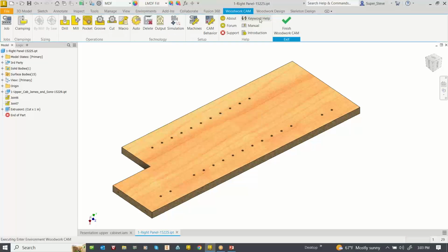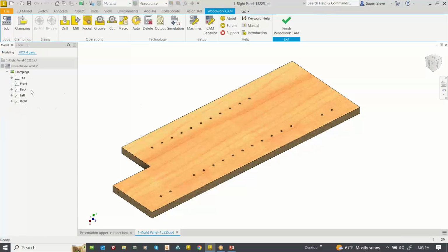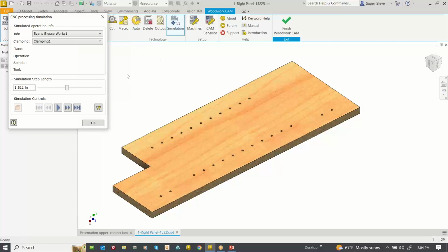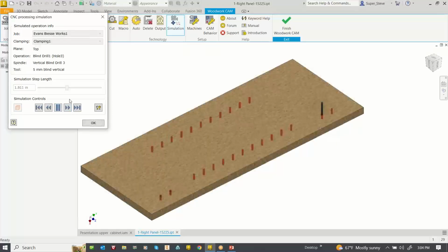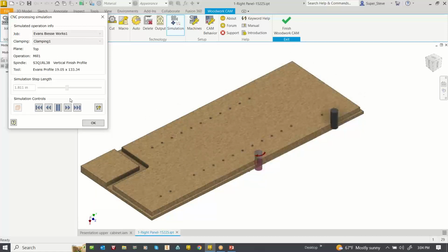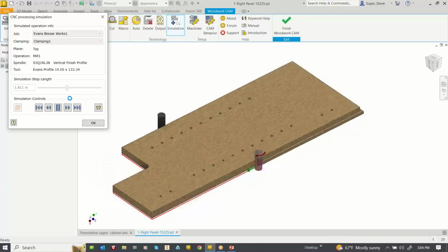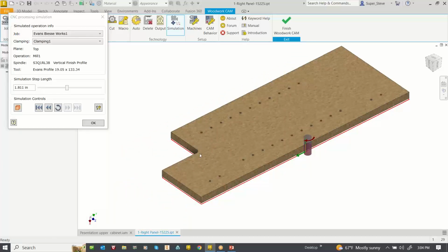Now let's take a look at what was just done. So you could see here is your milling, and I'm going to run the simulation. And the order in which it drills first or mills first, of course, is completely up to me. Did a good job. But I don't like that inside corner. Sometimes some of our accounts drill first, create some sort of relief here, and they have to play games.